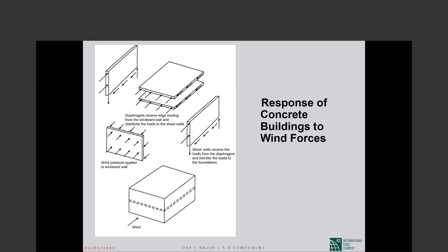Most concrete buildings are simple diaphragm buildings. Masonry buildings also can be, many times. Wood buildings probably are not, most of the time. So anyway, a simple diaphragm building is where the wind is transferred from the point of application down to the ground via the floor and the roof diaphragms. Okay.